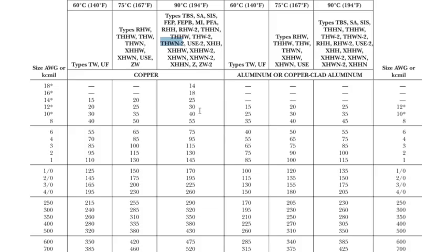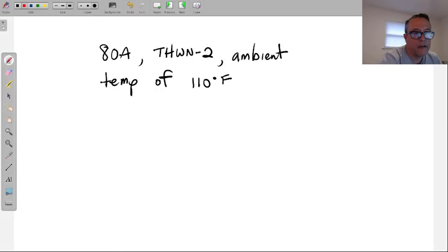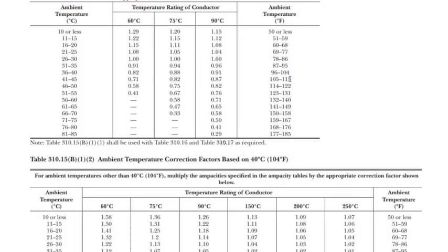And now I can go, all right, well, I'm going to need to cover 80 amps. So I can start somewhere here in the 95 or 115 conductor. So it'll probably either be a number 4 or a number 3 wire, right? Because 95 amps or 115, as I reduce amperage from this because of 110 degrees Fahrenheit, it'll probably land at one of these 2. So I can just pick one of these 2 and go, all right, let's go with the number 3, 115 amps. So we bring in 115 over here, and we're going to multiply that by the correction factor of 110 degrees Fahrenheit based off of the insulation, which is 90 degrees. And so we come over here to the table as we just did right now. This part should not be hard. We go 105 to 113, 90 degrees, 0.87 is our correction factor. And so that's what we're going to multiply that 115 by.